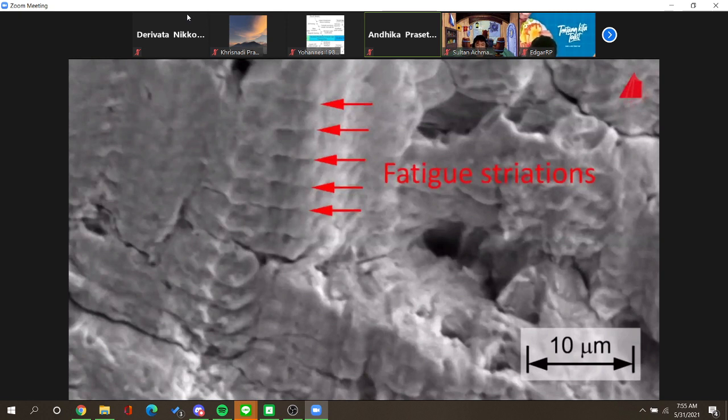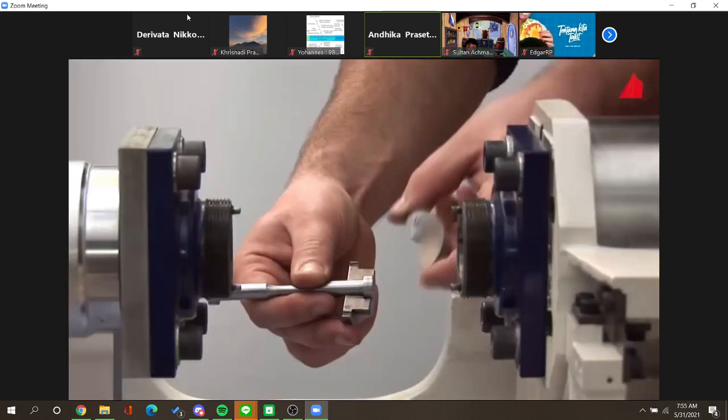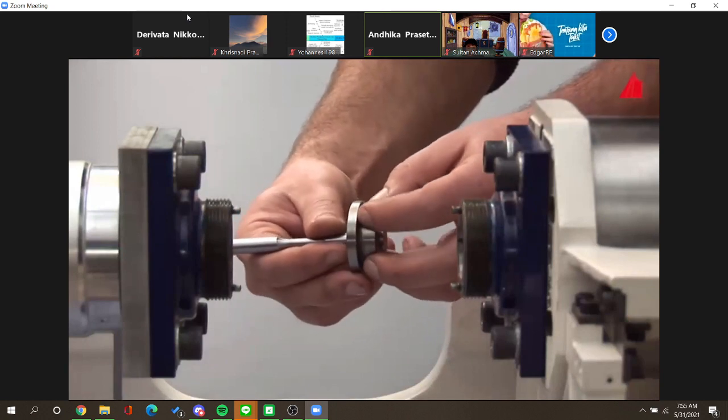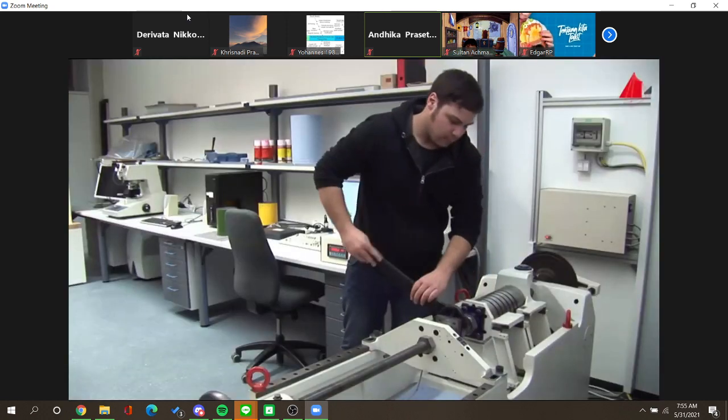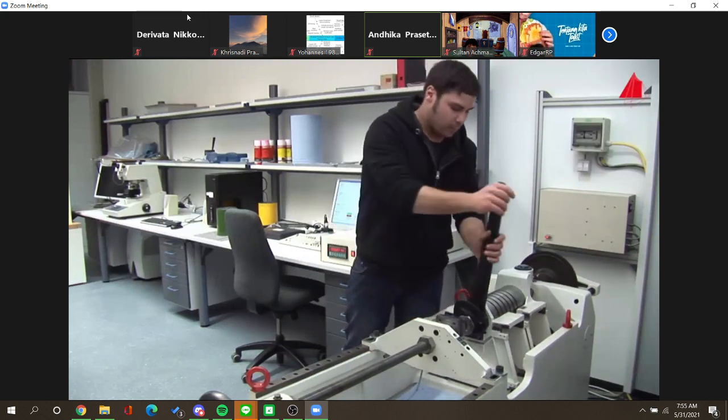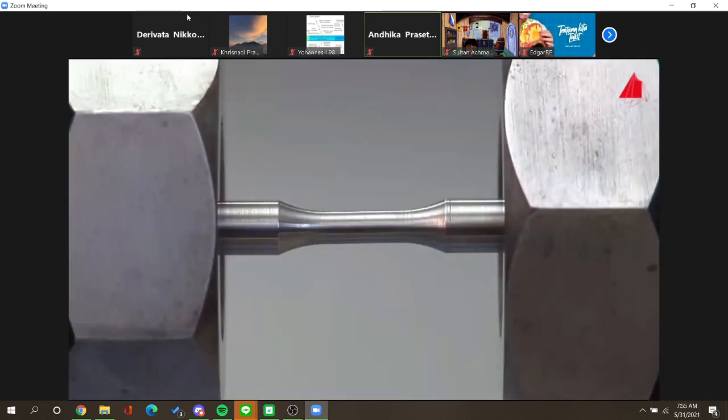Of course, now we want to know how many load cycles this material can endure with other loads. For this purpose, the material tester picks the next specimen from his supply and installs it into the fatigue testing machine. He chooses a higher alternating load for the second specimen, a tensile force of 7.5 kilonewtons and a compressive force of 7.5 kilonewtons. Under the increased load, the specimen is only able to withstand 43,600 cycles to failure.